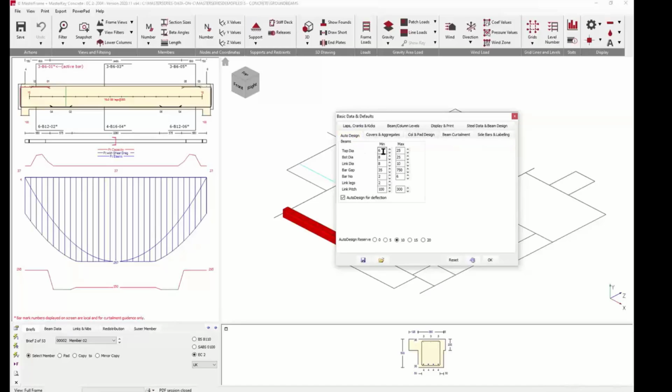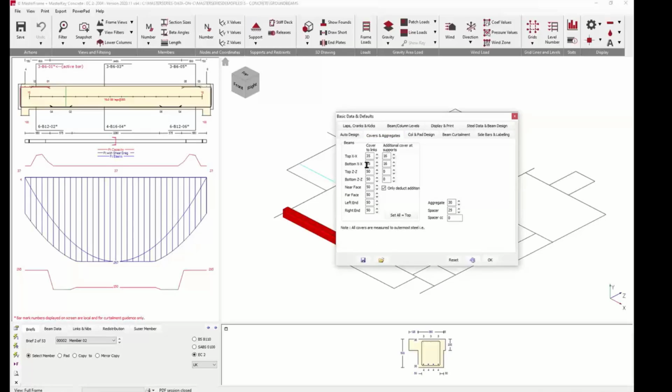We're going to use anything from 6s to 25s, a bit extravagant, and from 2 to 6 bars, and from 100 to 300. So I've opened it up, and I'm going to put in a 10% reserve, a little extra load factor for myself. Covers, we're going to go for 50 bottom and 35 top.